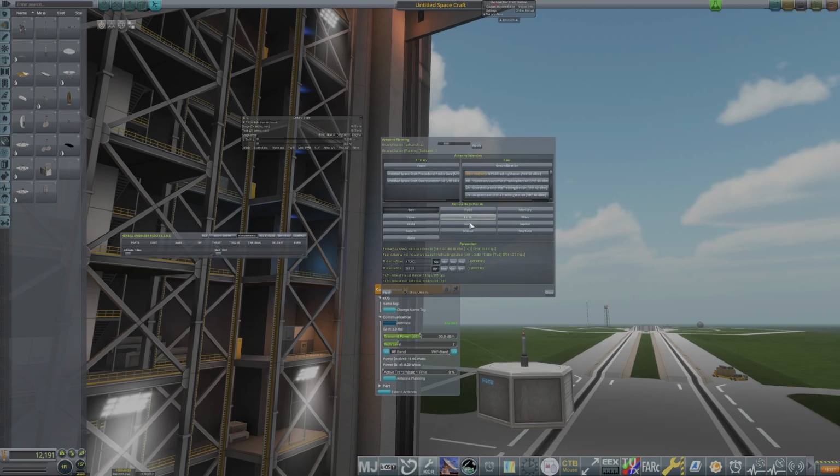So what I would usually do then for those relay networks is I'm going to take a VHF band antenna and I have one on my spacecraft. So usually the spacecraft that I have in low Earth orbit is not the deep space probe I'm flying, because that's just a bus that's there to inject me into that orbit. And then I release the probe. So I have two different antennas there. I have one in the VHF band for the lower Earth orbit and another antenna for my spacecraft.